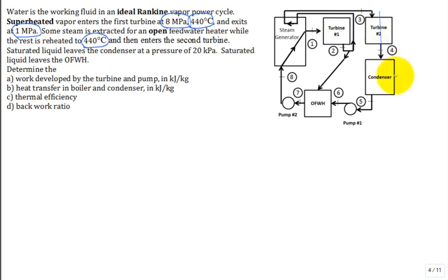And then the condenser pressure often is dictated by your cooling water. How cold is the lake that you're dropping it to? Or how about the outside ambient air? You have a big cooling tower, evaporating in a cooling tower. You don't have a lake. Or you have a bay, or they put the power plant right by an ocean or a big river.